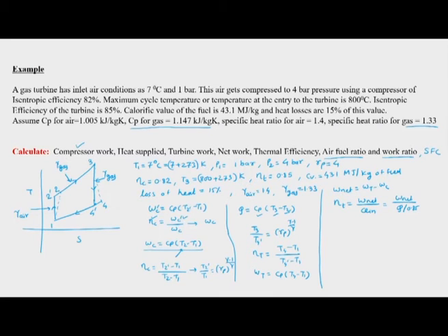Basically this can also be treated as combustion chamber efficiency. So Q is actually received, but Q in is practically the chemical energy which was available, and only 85% was received. So basically 0.85 is equal to Q upon Q in. Okay, and then that would help us in finding out the thermal efficiency of the cycle.